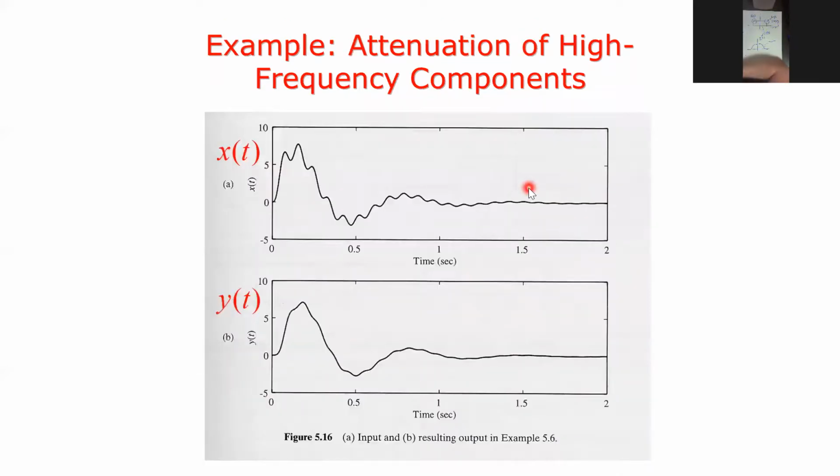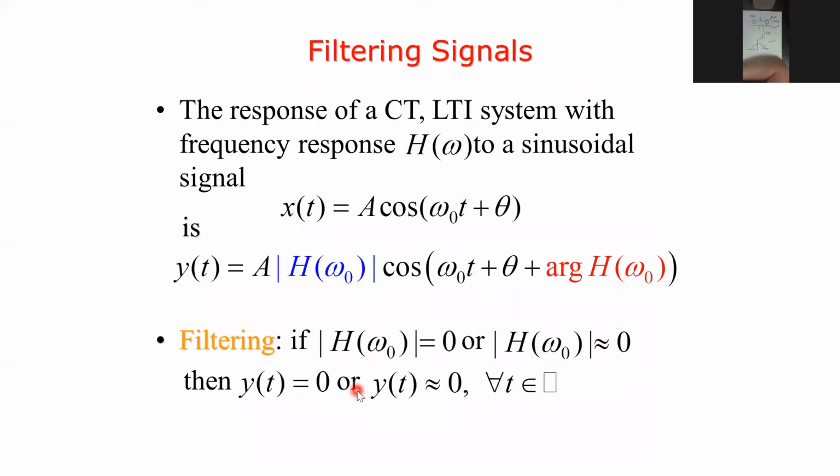So here we are talking about the smoothing property of the low pass filter. For example, here is a signal. This signal includes a lot of sharp edges in the time domain. Whenever it passes through a low pass filter, you can see that we now have smoothing features for this signal, because we get rid of the high frequency component of the signal. You can filter different types of signals, with different types of filtering processes, depending on whatever you need.